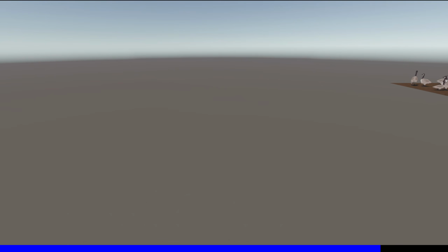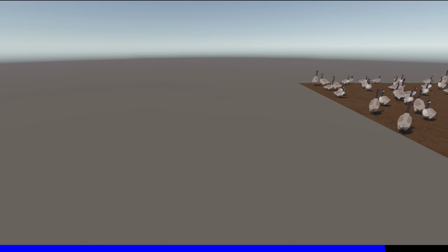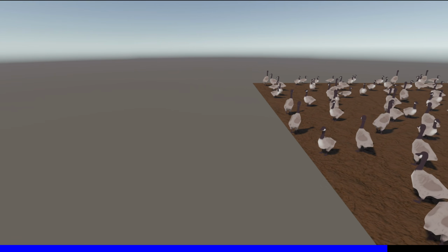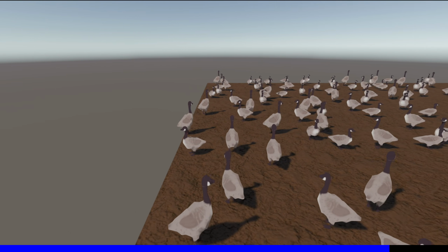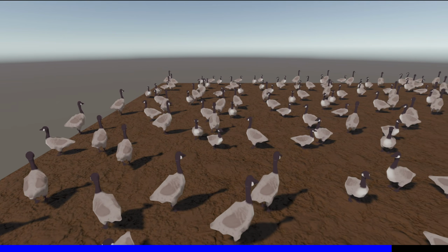So, what are the advantages of doing things with procedural rendering? Well, it's savagely efficient, and if you won't be adding, removing, or moving any of the grass meshes, you can just run the compute shader at the start, taking a huge amount of work away from each subsequent frame. It's also very easy to swap out the grass blade mesh for any other detail mesh. A rock, a bush, or a tree can be spliced in and it'll work just fine. Unlike the geometry shader approach, you won't need to totally rewrite the shader.